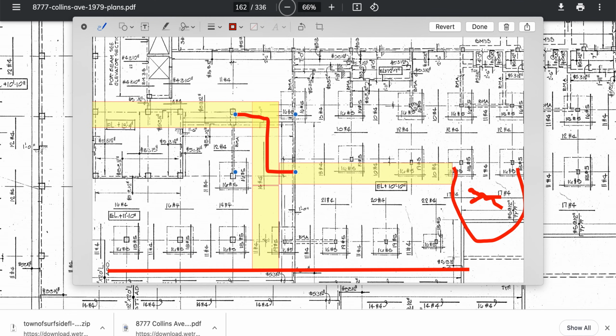I'm going to talk to you about tributary things. I'm going to do a video on that, and I'm going to show you how that ties in. Tributary, to give you a cheat, I want you to think of your floor joists in your house. If you live in a wooden house, you have your floor joists spaced, let's say, 16 inches on center. I want you to remove the center joist between three joists. What happens when you remove that center joist? Your floor sags, doesn't it?